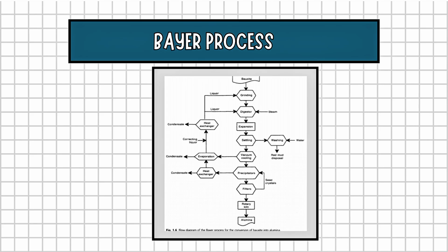So yung next is grinding. The bauxite is crushed and ground into very fine particles, meaning to say ginagawang pino ang bato para mas madali itong matunaw sa chemical solution. So, what's its purpose? Its purpose is to increase the surface area and make digestion faster and more complete.